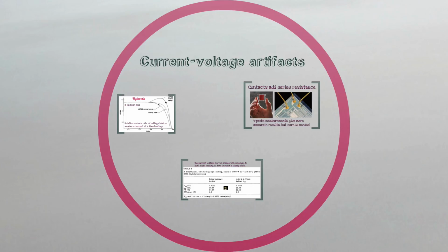The other thing, of course, we have to be wary of when we do measurements is artifacts. I'm not sure if Bill mentioned, but when you do these IV curve measurements, there are all kinds of strange things that can happen. The most common thing that we see if you buy a cell and try to measure it is that instead of seeing this nice nonlinear curve, you see a straight line, which usually means that there is a huge series resistance in your circuit.